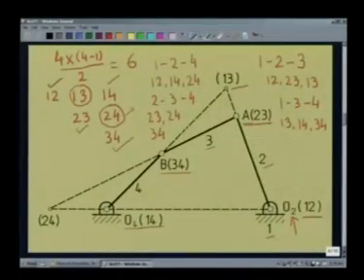Out of these 3, we have already located 2, 3 at A, 3, 4 at B. So, 2, 4 must lie on the line joining A, B. As a result, 2, 4 is located at the intersection of the line O2, O4, that is the line joining 1, 2, 1, 4, and the line AB, that is the line joining 2, 3 and 3, 4.